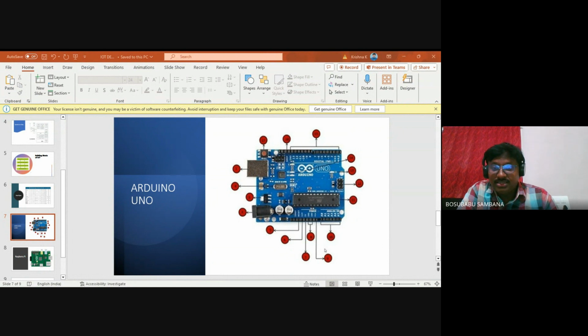The main IC on the Arduino is slightly different from board to board. The microcontrollers are usually of the Atmel company. You must know what IC your board has before loading up a new program from the Arduino IDE. The information is available on the top of the IC. For more details about the IC construction and functions, you can refer to the datasheet.